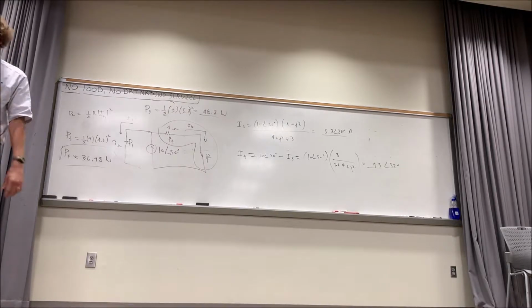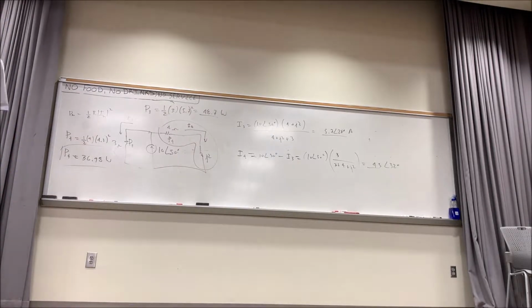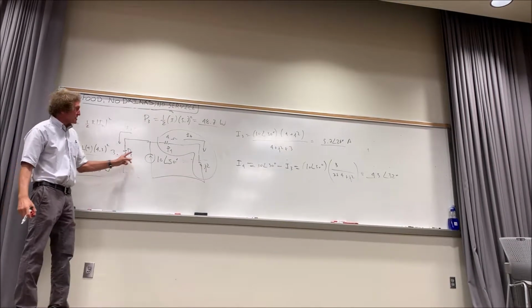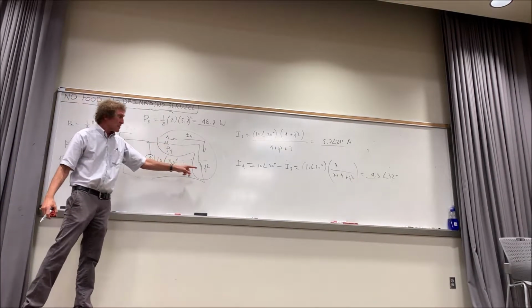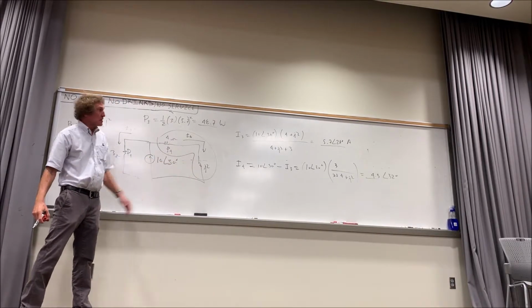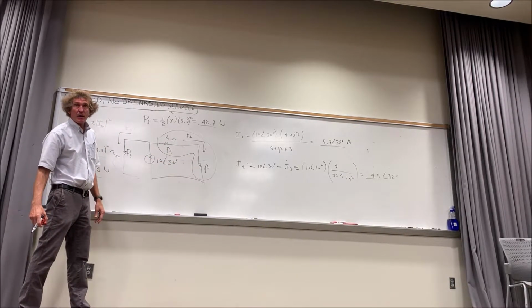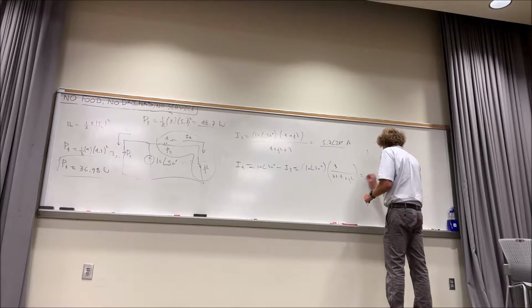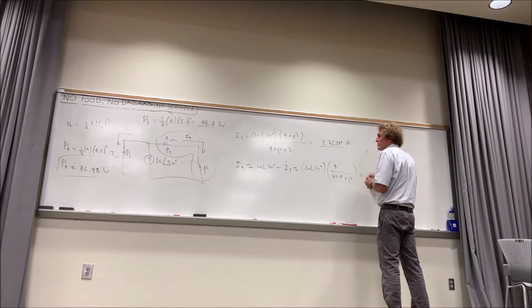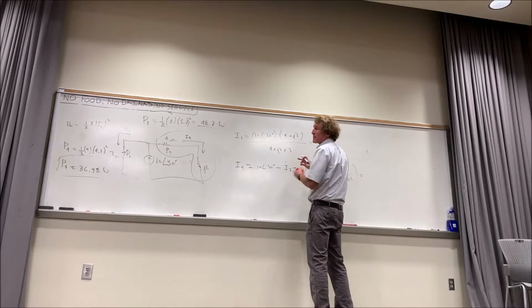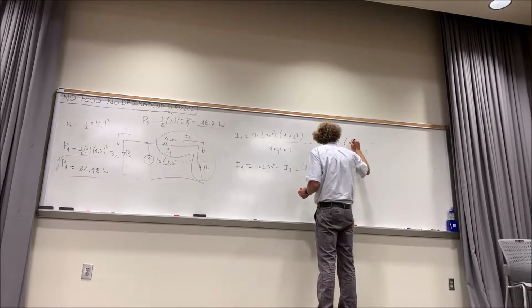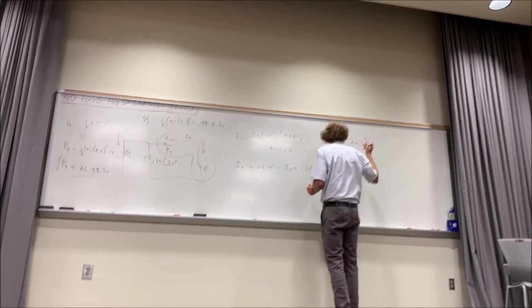Yes, sir. Those answers are different than in the book. Is there a reason why? You got me. Are these numbers right? Is this 3 ohms? Yes. Is this 4 ohms? Yes. For 4 ohms, they're showing 33.95, and for 3 ohms, they're showing 56. Wait a second, I think we found the problem. Go ahead. I switched it to 6.143. Oh, I'm sorry, I3. Get the I3. Just write it down. 6.143, angle 40.662. Just 40.6 degrees.